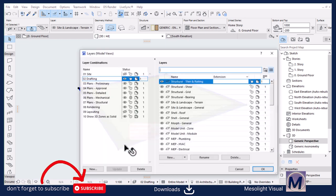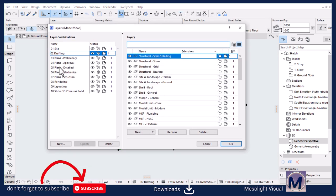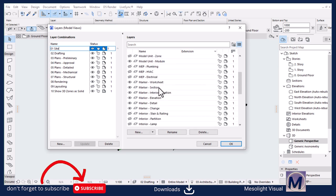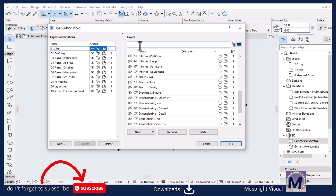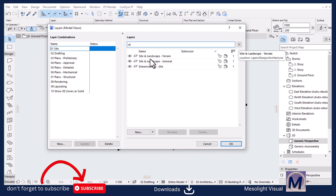Because it's important to work with layers. So in the layer settings, we have layer combinations this side and then layers. So the layer combination that we're working with is going to be the site. So I'm going to select it and then move this side to the layers, and then let me search for site. Yes, because I want everything that comprises the site to be under site landscape terrain.